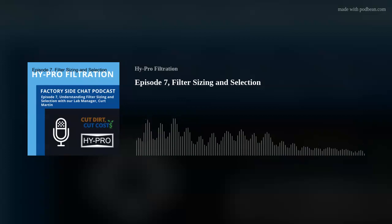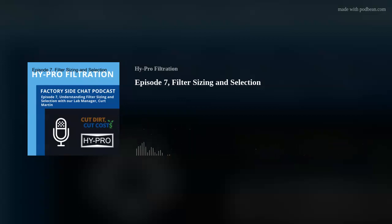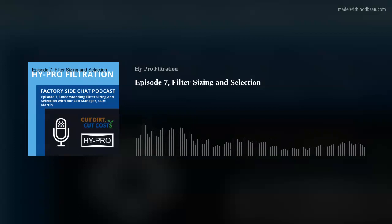So let's center on pressure initially, because you and I both notice that this is a problem that we see often: system pressure versus collapse pressure of the filter element. Do you see a confusion with the customers often on those two? Yeah, we do see that from time to time. So the system pressure, basically, you're looking at the upstream pressure, upstream of the housing.